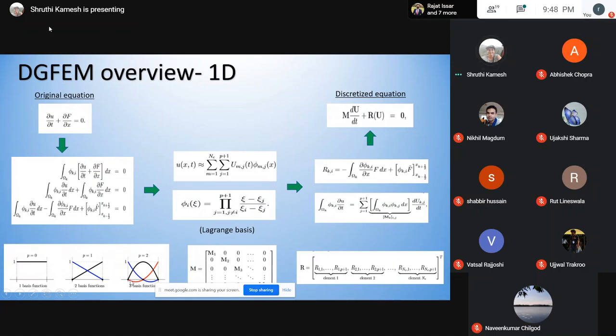Whereas for this, which is to some extent related to mesh refinement, at least the visualization part of it, in each element I want it to be second order. If I want my solution to be second order accurate, I say that, okay, I want to approximate it using the values of 3 points. So that's why you take p equals 2 over here.